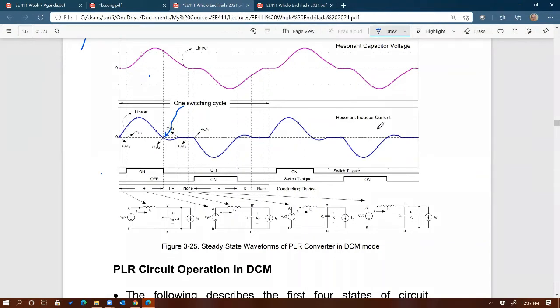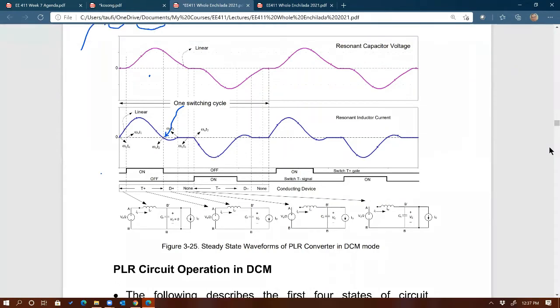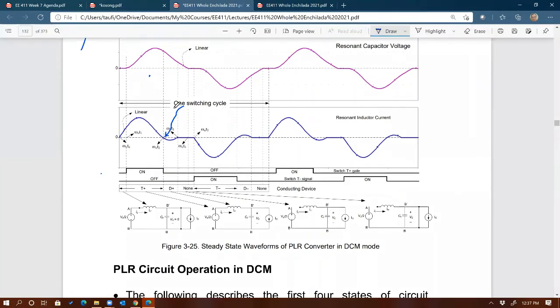Well, that means semi-controllable, right? Because if you have a semi-controllable switch, you are able to tell the switch when to turn on, but not to turn off. In other words, the switch will turn off naturally at 0 amps. And that is a perfect condition to use a semi-controllable switch, right? Because the switch turns off at 0 amps naturally, following a sine wave.